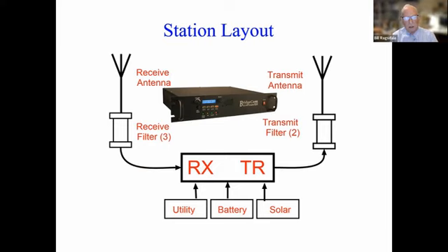Into the receive side, the RX side of our repeater, the modulation is converted back to audio. That then remodulates a carrier on a different frequency for the transmit side, and then it goes out through the filters and up to that antenna.